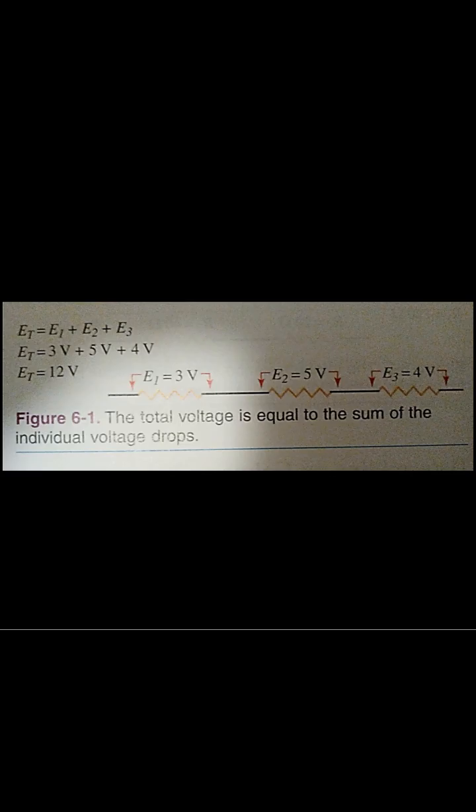Voltage in a series circuit is added. Kirchhoff's law. This means you must add all of the voltage drops together to get the total voltage. Looking at figure 5.2, you have to add the voltage drop across each resistor to get the total voltage, or ET.